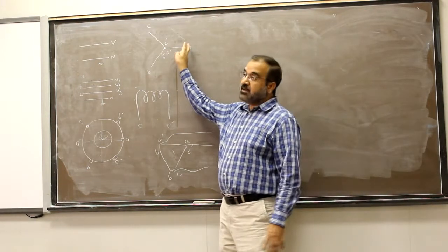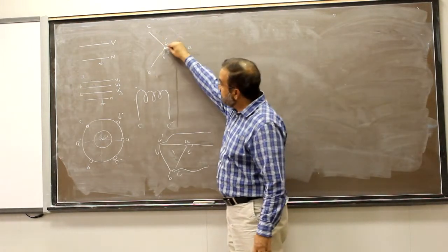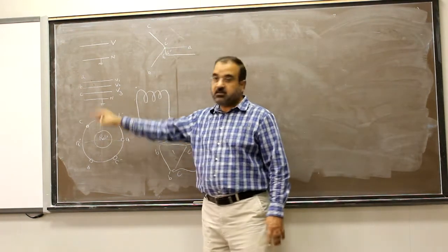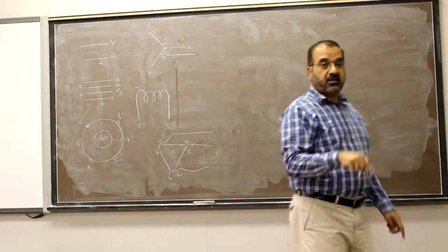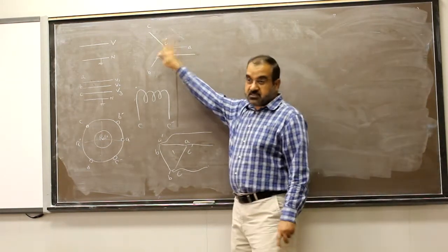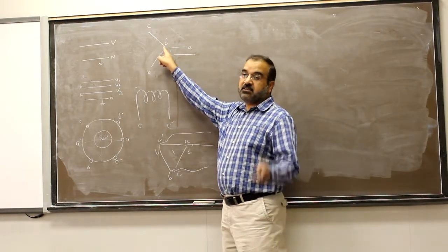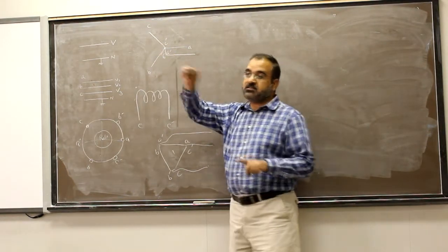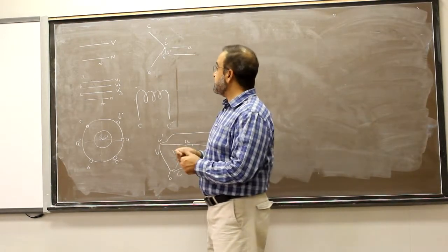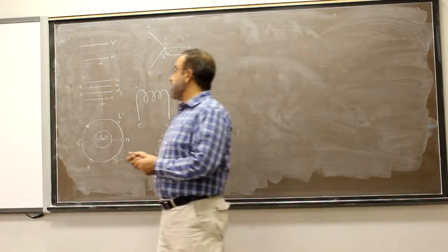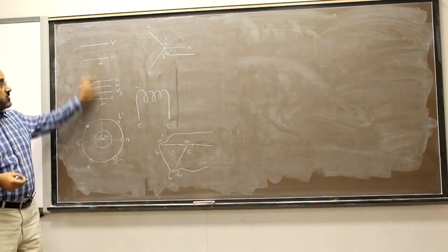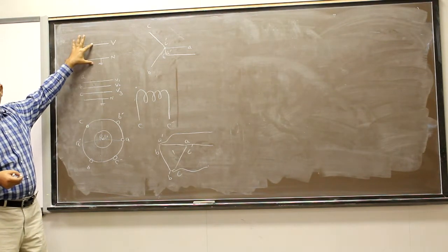Here you get either 3, or if you need you can take another one as a neutral conductor, which is this one. Now why we call this a neutral conductor, I will explain after some time. But right now, just say that this point is a neutral point. Neutral means 0 voltage, yes? Now the question is, when I told you there is a phase, so phase is between line and neutral, yes?